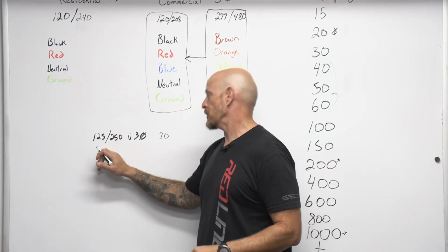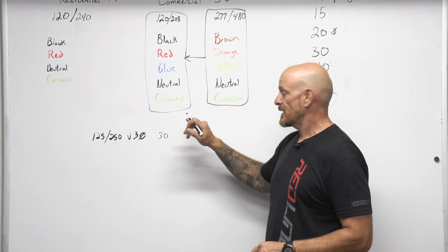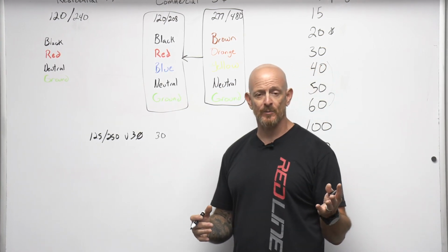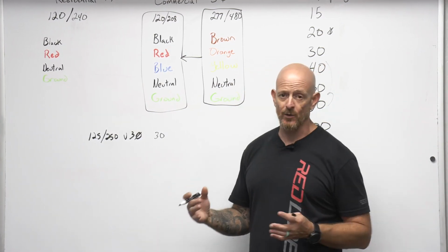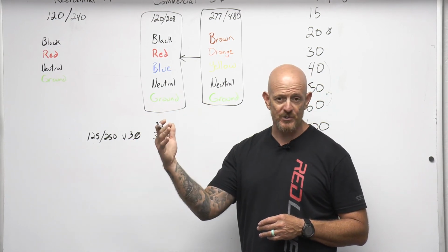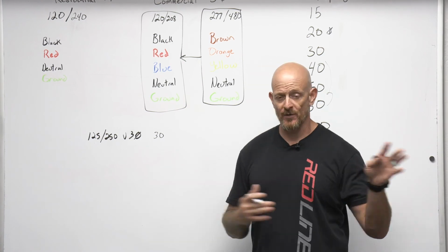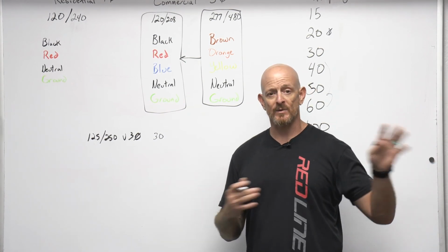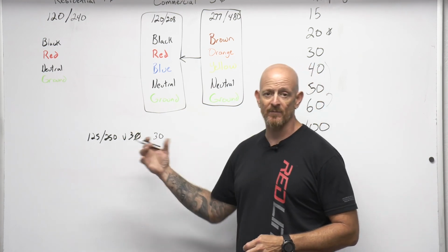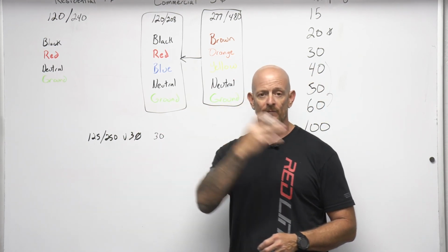After finding out the power requirements, voltage, phase, amperage, the only other thing we need to consider, and we'll find this out typically when we do our site visit, is the distance. So distance does play a factor in, so there's a voltage drop, and you need to calculate those things. So the farther we go, the more resistance we need to add. We need to increase the wire size to take the same amount of amperage for longer distances.